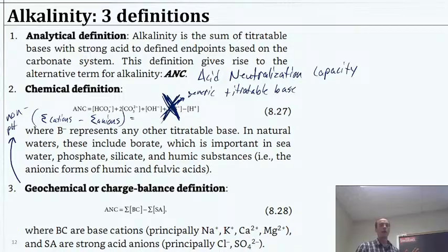So if we got rid of that, and we wanted to change the pH of our system, well, we know exactly how much alkalinity we have based on this equation. So if we needed to change the alkalinity some amount or adjust the pH, which is over there in the corner, right? If we wanted to adjust that, well, we know that it's going to relate directly to that net strong base term, right?